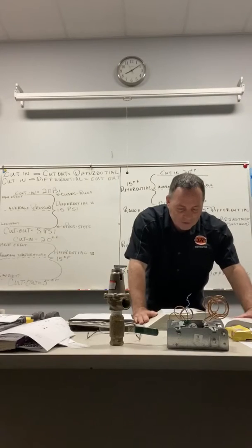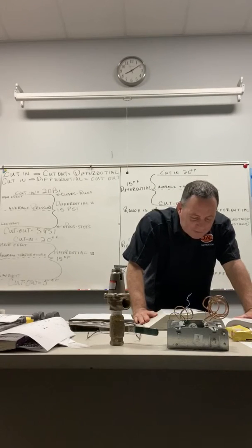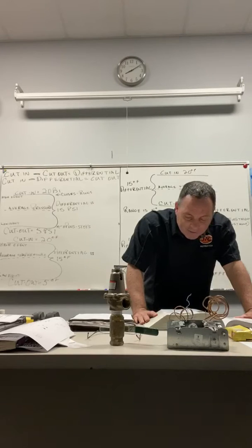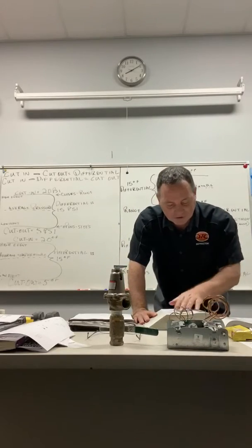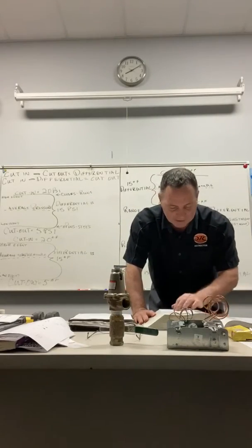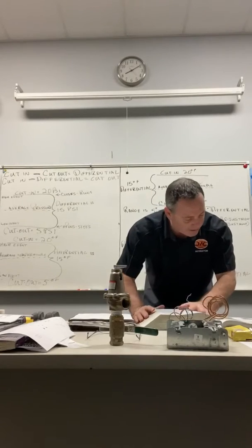One way it says on 353 is the pressure switch can function as an operational device or a safety control. In fact, a pressure relief valve is a safety control, which will open if the pressure in the hot water system reaches unsafe levels. Now they have a little bit about water controls, so I'm going to skip this right now until we get a couple of pages ahead. But let's talk about this real quick.